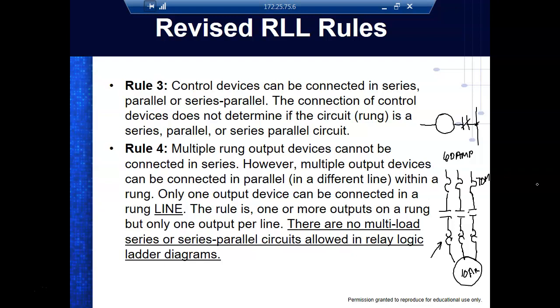It lets the motor start, but if the motor doesn't start, then these sensors will sense it. It'll open this contact up, and let's say this is M, and these down here are M. It'll open up M or make M drop out or de-energize and pull power off the coil.